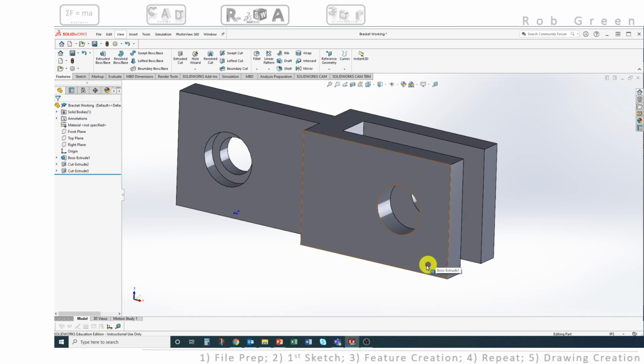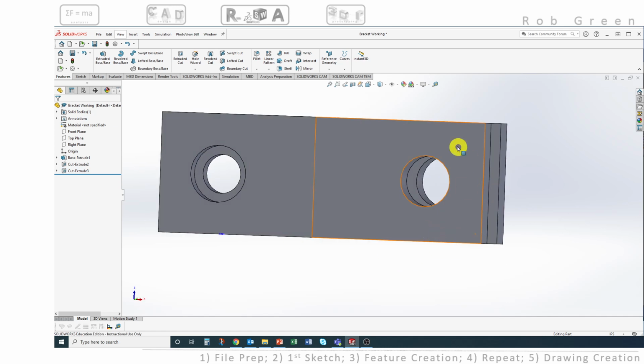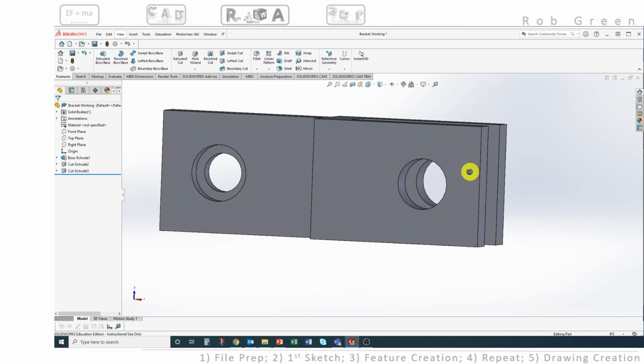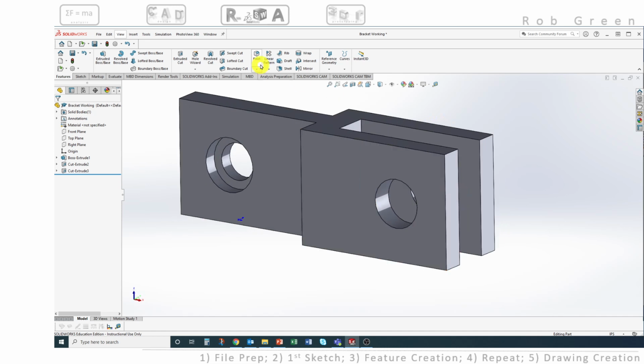So this last thing that I need to do in terms of geometry is round off this end out here. Of course, I have two options. I could sketch on this surface, and then I could draw that arc and enclose a box out here and cut away with the extrude cut command the outside edges here. But of course, there's also another way, and there is this command up here that I can operate with in 3D on an edge, or actually a surface, but we'll use an edge. And it is a fillet command.